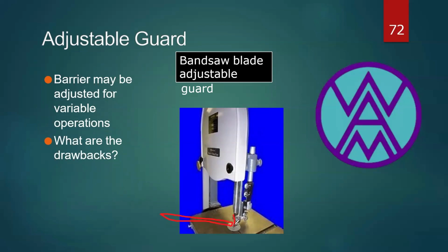Okay, this is the blade. What if I have a big plank, big something to cut? I will rotate this part, loosen it, move it upward, lift it, and then this blade will be long enough that I can cut such a part.